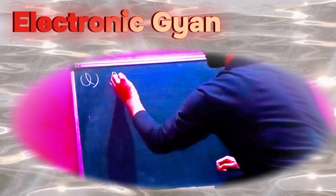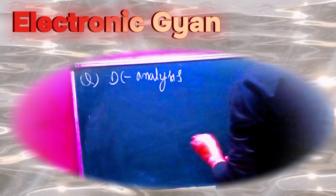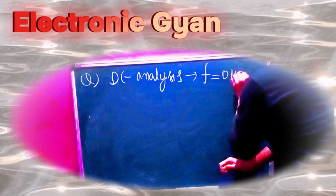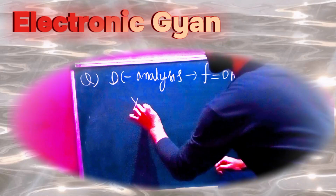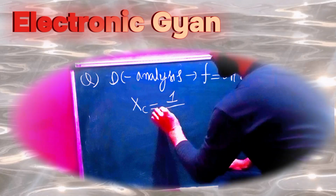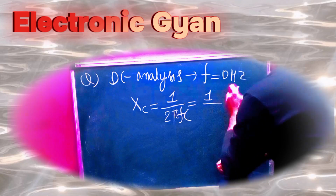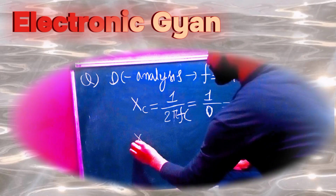In DC analysis, what happens? DC means frequency is 0 hertz. If frequency is 0 hertz, then what is the impedance of the capacitor? Capacitive reactance Xc is equal to 1 by 2 pi f c, where f is 0, so Xc is infinite.